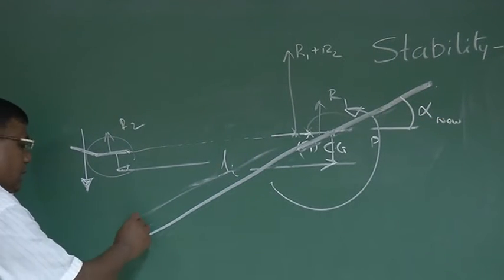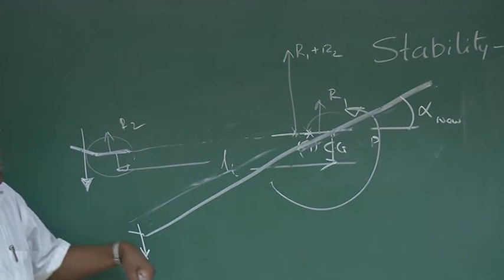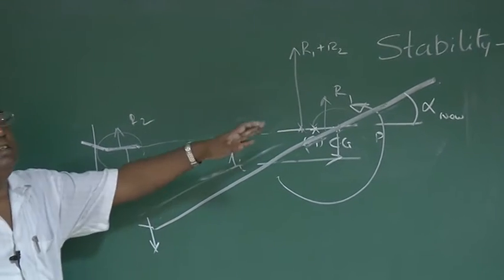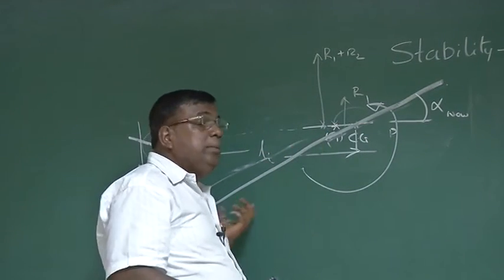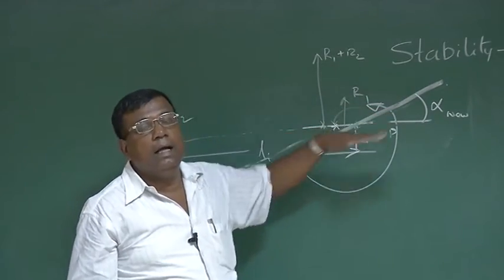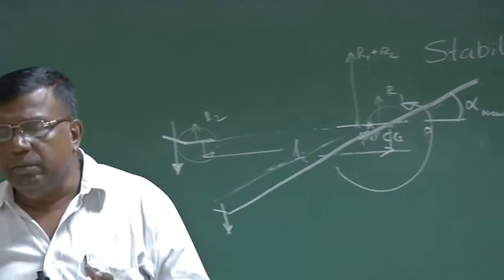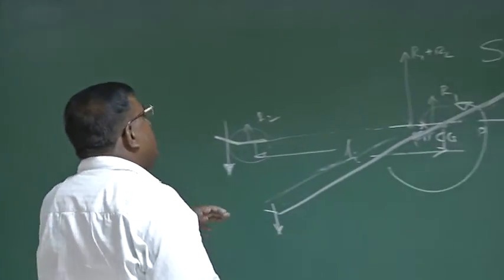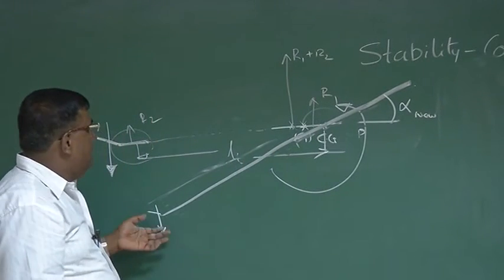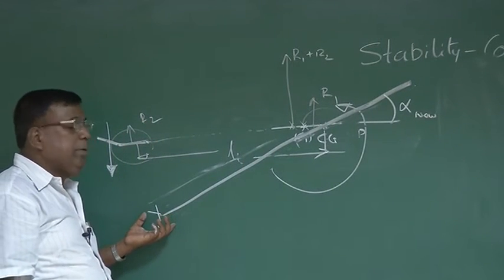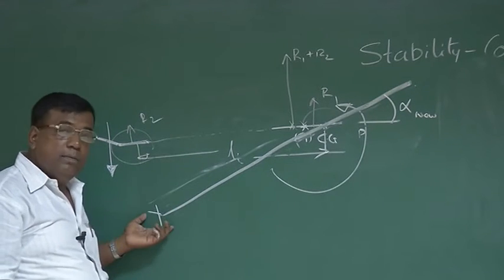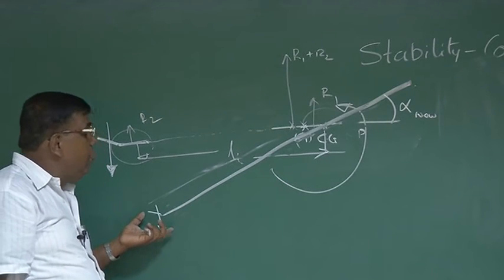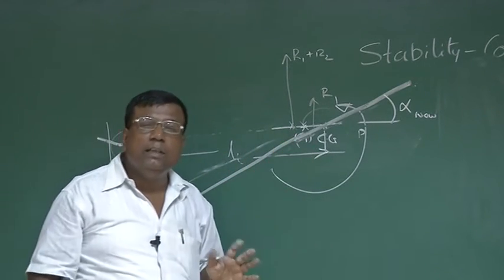And we are very clear that somehow we have to apply this moment through this force to hold this airplane, because otherwise, since it is statically stable, if we don't have this force, it will try to come back to the original alpha. And this is, in a very holistic manner, the control problem. Okay? You can very well understand how much you can turn will also depend upon what is the force generating capability of this surface, or what is the moment generating capacity of this whole system. That will be decided by not only the force but also the moment arm. So these are matters of detail, right?